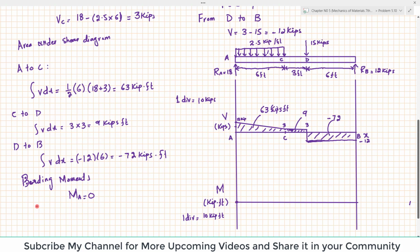Clear? At point C, we have the moment at point A plus the moment of this area. So 0 plus the area under the shear force diagram, which is this 63 kips into feet. So it will be 63 kips into feet.